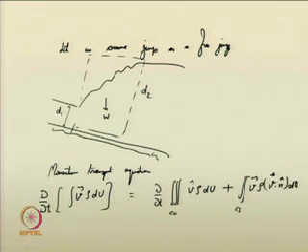This we have done earlier also, right. That is suggesting the rate of change of momentum in the control volume. This is equal to the rate of change of momentum stored inside this volume plus the net outflux of the momentum across the control surfaces. Now, we have two main control surfaces, this on the left and on the right. All other control surfaces are not allowing the momentum, as this is predominantly a one dimensional case. We will continue with this portion now in the next lecture.